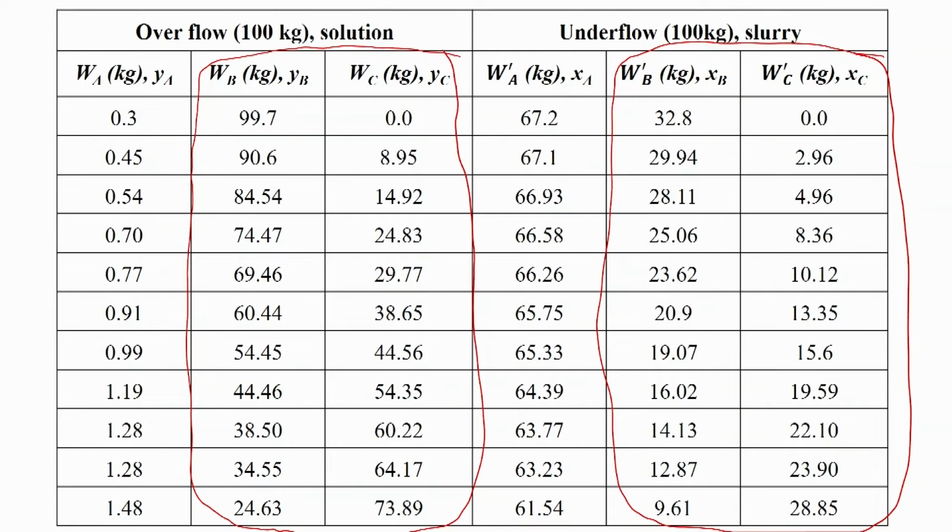That is very crucial. But remember that whenever this type of correlations are given, this Y_c is in equilibrium with this X_c, so these are also equilibrium data points, or tie line values.